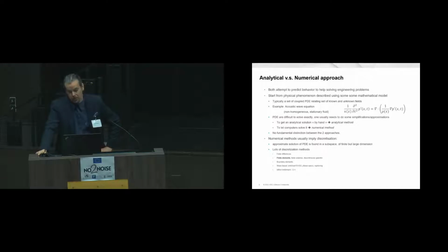You have maybe the earliest one, the finite difference, very well known, not much used in vibroacoustics. Then you have finite elements, almost as old, which I will speak a lot about, and I think they are the current main generic technique used in commercial software for low frequency approaches. You have finite volumes, discontinuous Galerkin approaches, which are somewhat similar to finite elements and much more used in fluid dynamics.